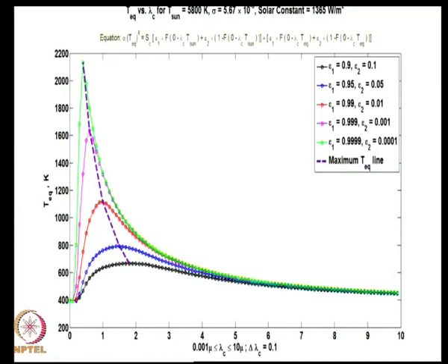If you recall from the previous lectures, the sun's radiation lies mainly between 0.4 micron and 4 micron. If you keep the cutoff wavelength at 4 micron, you see that the temperature that you get is around 600 K, whatever the values of these emissivities. So, what it means is that at 4 micron, the high emissivity in this region is leading to sufficiently high losses from the surface that the temperature cannot really go beyond 600.